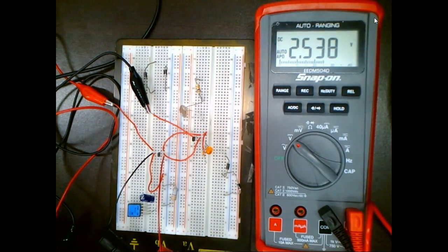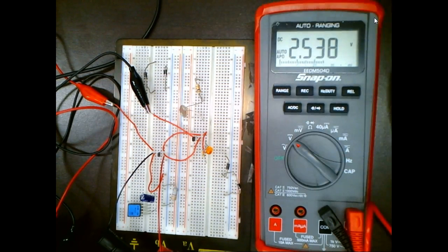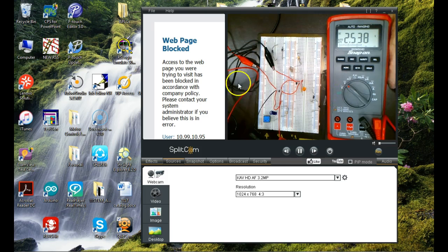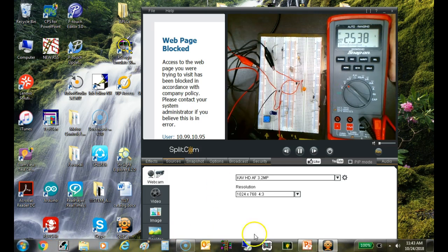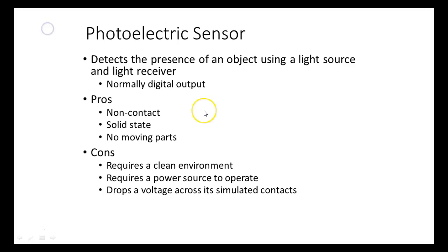What happened? Okay, so now the receiver, we can use that to sense an object, right? So if I've got a light being transmitted, and you see this all the time at your house, get out of the front of the TV, I can't change the channel, right? Well, what you've done is you sense their presence, right? Because what they're doing is they're breaking the beam between you and your TV, right? And that's a sensor, so that's one of the main things we have. And guess what we call that guy? Through the beam. Some of them call it direct scan, but we'll teach you this as through the beam.